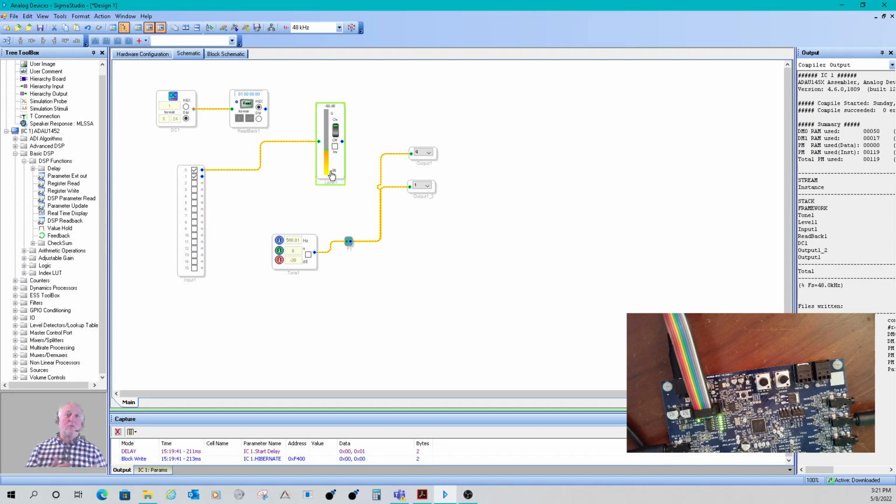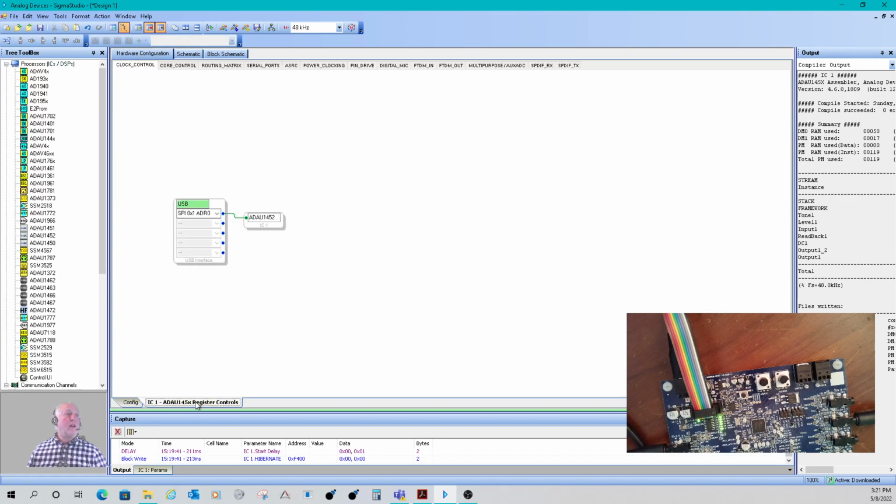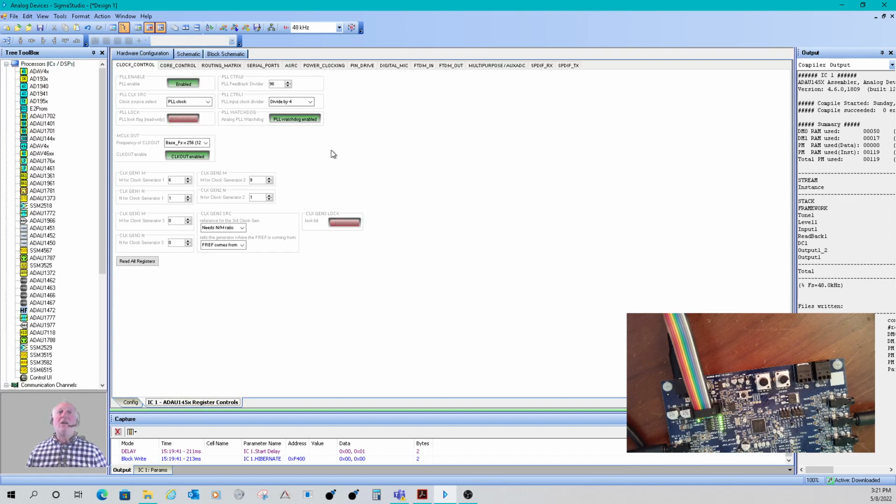Likewise, oscillators too, and filter coefficients for the cutoff frequencies and such, or the center frequencies. That all depends on the sample rate, and so the compiler needs to know what the sample rate is to compile the code properly. So it compiles the code and downloads it to the DSP. It has no idea what the DSP is really set for. SigmaStudio does not have the intelligence to go into the hardware config and the register settings and understand what to set up here.